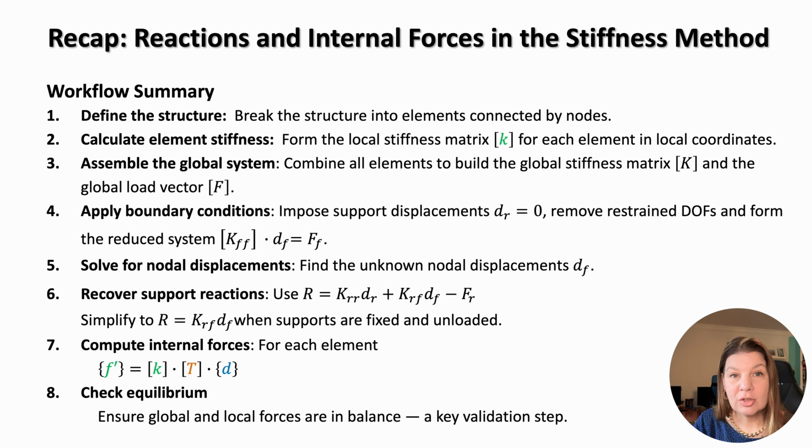We start by defining the structure, calculating element stiffness matrices, then assemble the global system and apply the boundary conditions. Once solved, we recover the nodal displacements, support reactions, and internal forces, and finally, we check equilibrium. So this slide is simply a summary of the full method we'll now implement in code.